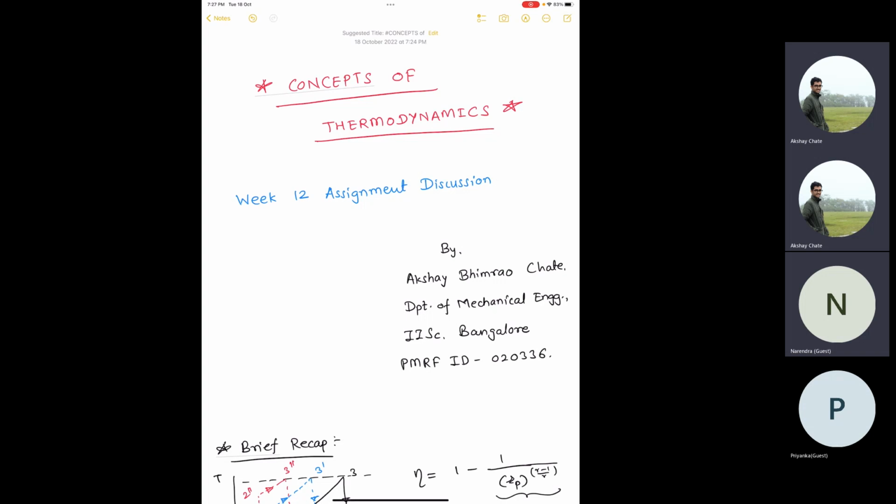But you explained very nicely, taking each separately. Still I remember that if the piston is without a spring and moving, the process is a constant pressure process. If it is with a spring, then it follows a linear relation between pressure and volume. Or if there are stops, then up to the stop the pressure will increase, so the volume will remain constant. Really, sir, you have given a very useful concept. I really enjoyed it, sir. Thank you very much, sir.